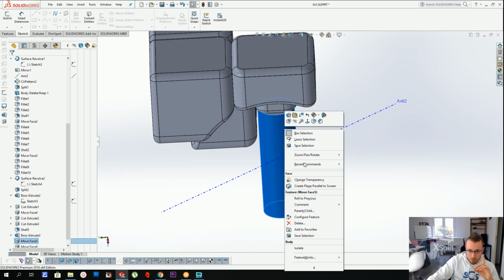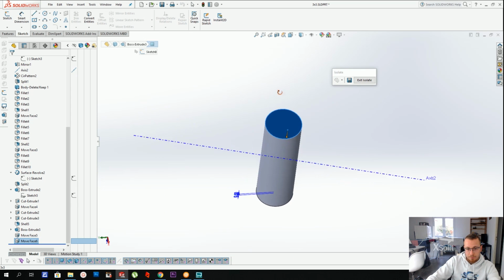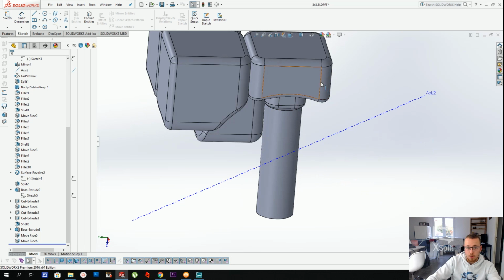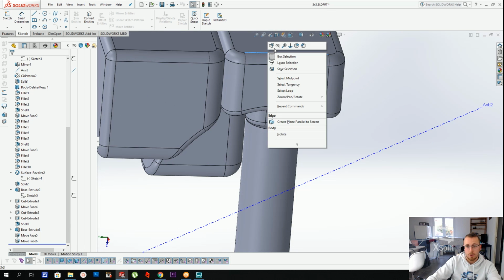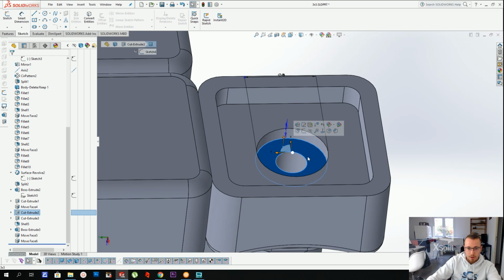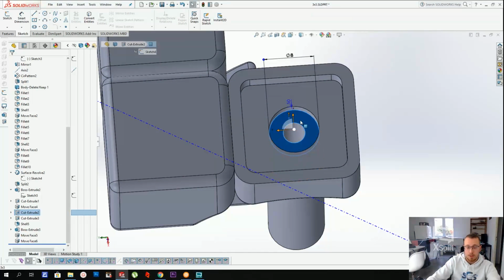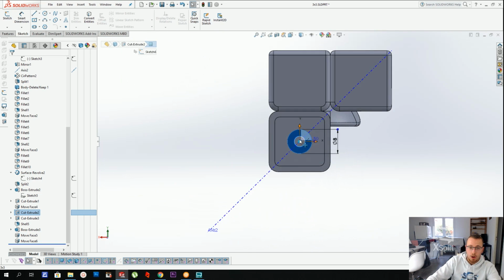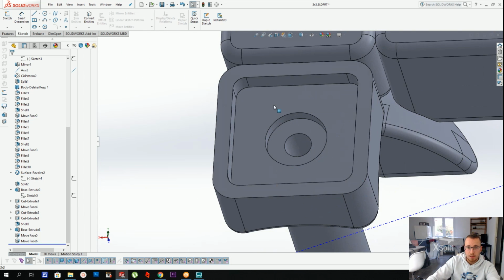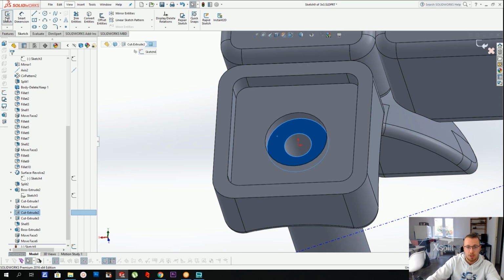Now before we do that repetition, we want to do something. So we want to create a hole for the screw inside the core. So here I'm going to hide the cap because it's bothering me. And here, since this is a plane that's right over where the screw is, we're going to draw directly on that surface. It can be here, there, anywhere, really, but it's fine if we just create a sketch here.